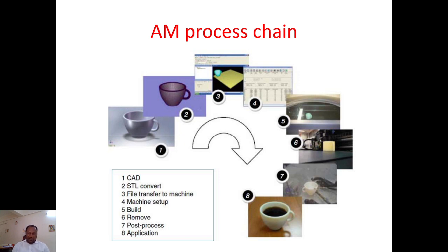Once removed from the machine, parts may require an amount of additional cleaning before being ready for use. Any weak areas at this stage may have support structures. Sometimes in the additive manufacturing process, for overhanging structures like that, we definitely need some support structures. These must be removed, which requires time and care with manual manipulation. That is why the additional treatment is required.